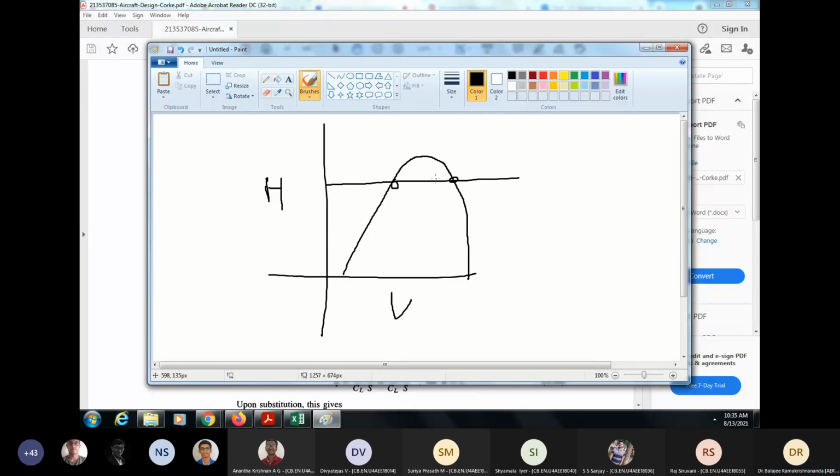Here. Ceiling velocity can have only one velocity. So you can have a lower velocity also. Yeah. Okay. But then at ceiling, the CL will be different. At this stage, you don't know what CL to take.